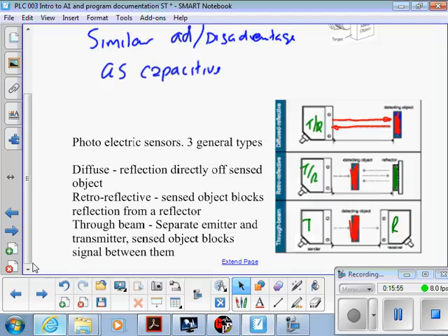The honest answer from me to that is I don't know, but infrared I would think. Not visible light in most cases. Ones I've used. You got any that got visible light? The light curtain ones do sometimes have. If they're like the safety light curtains, but these ones can't see anything. So you can't look for a spot or a dot on that reflector because it isn't there. You kind of got to just move it until they line up, or use a piece of string to get them lined up, that type of thing. Or a straight edge if they're close enough together.